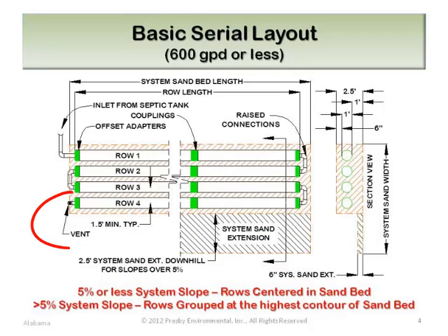A vent must be attached to the end of the last row in the series. This ensures air is drawn through every foot of Presby pipe. It's important to note that the row spacing is a minimum. The designer is free to increase this spacing if they desire.